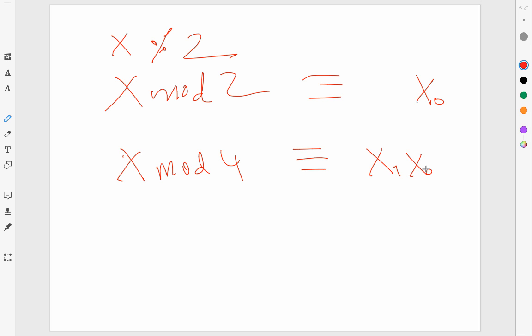So anything that you wish to do, like trying to see whether the input went from 0 to 1, 1 to 0, or something happened, should all fall out of your next state and output logic. The clocks you should not be messing with. That's the other statement I wanted to make. Let's see what other things came up.